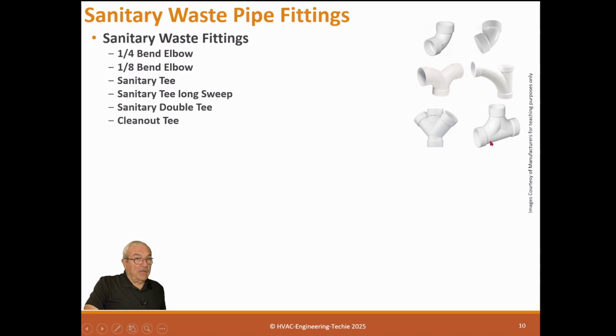We also do this a lot of times with a tee, make them up. Instead of buying one, we build one that's got a tee here and a tee here, and then they go up quite a ways at 45, and then they go out with one of these upside down to get it. So you can build these. You don't have to buy these. And, of course, couplings.